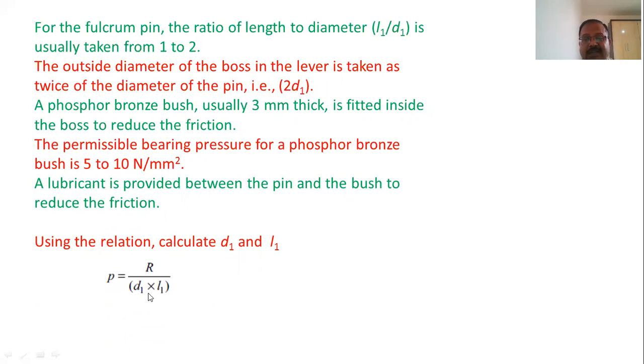And for interchangeability purposes, if we have designed a pin at the load point of higher diameter, the same pin can be used for the fulcrum, and the same pin can be used for the effort also. So you have to consider the higher value of force over here. But as we are talking now about the fulcrum pin, we will be taking the load which is acting on the fulcrum pin, that is the reaction on the fulcrum pin.